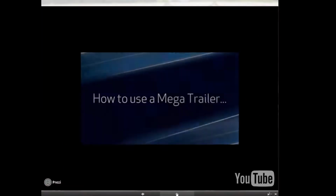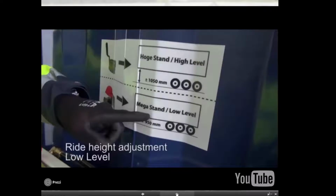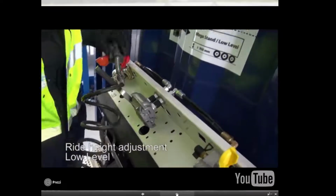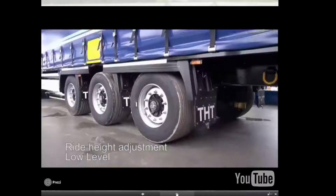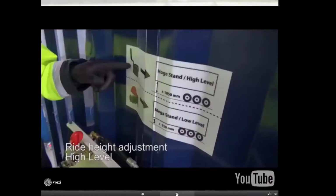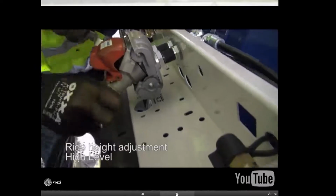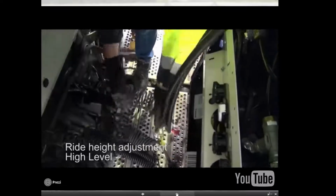We will now watch a movie about how a Mega trailer can be used. In order to transport the Mega trailer, the ride height needs to be set to a lower level with the air suspension system. Remember, this needs to be done to maximize the external height. Now we show you how to increase the level of the Mega trailer. This level is used in particular countries where we face fewer limitations related to the external height, and thus a standard truck can be used.